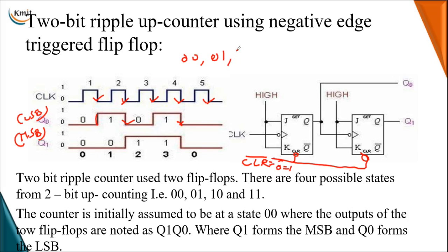So on your third clock pulse, Q1 is shifted to 1 and Q0 is shifted to 0. On your fourth clock pulse, you have logical 1. Now just by observing these successive states, the difference between them is logical 1, hence it comes under the up counter.